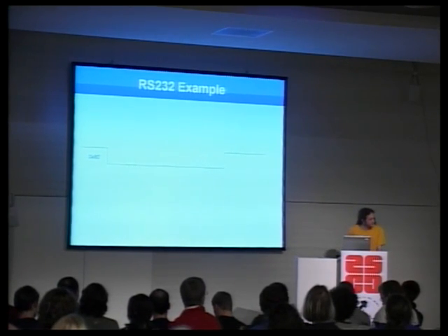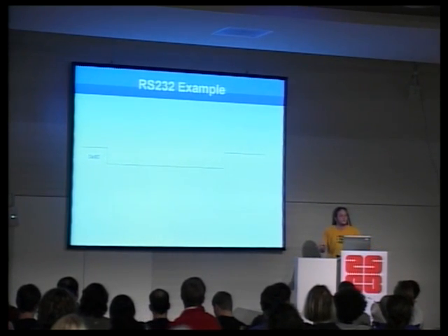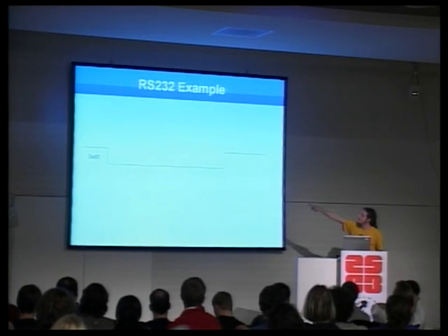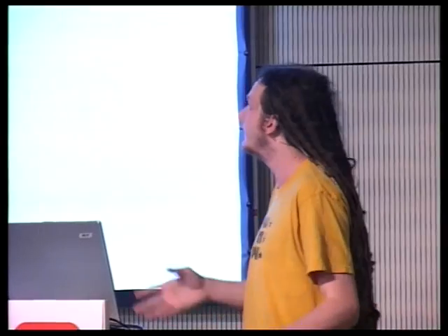For what? Make it wake up? Not quite. This is how it determines how quickly the transmission will be. Think of it as the difference between the 2 edges. If you divide that by 8, you get the width of 1 bit. So that's what it does. It starts its own timer by measuring the difference between these 2 edges, and that's how it knows how quickly to speak to you.